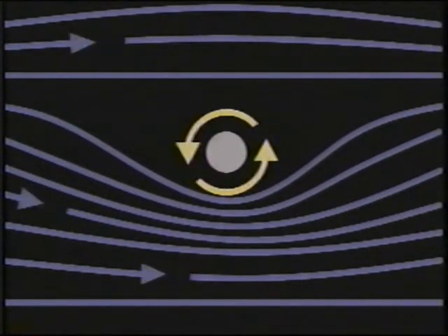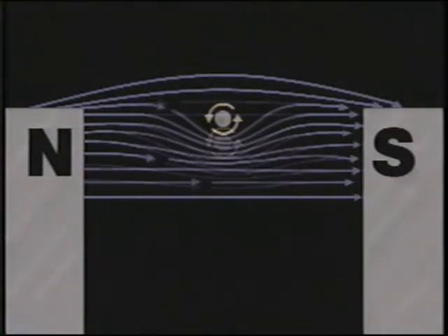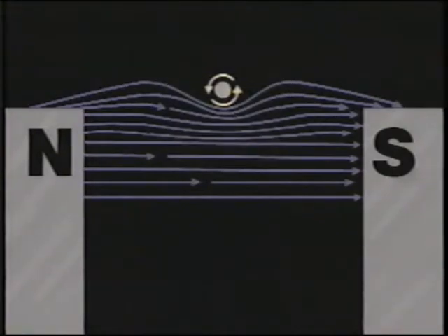The result of this difference in flux line interaction causes the conductor to be pushed by the strengthened field toward the weakened field. The magnetic push continues until the conductor leaves the field of strong flux interaction. Magnetic push from stronger field to weaker field is used to create movement in an electric motor. Let's see how the motor is designed to convert magnetic push into a rotary motion.